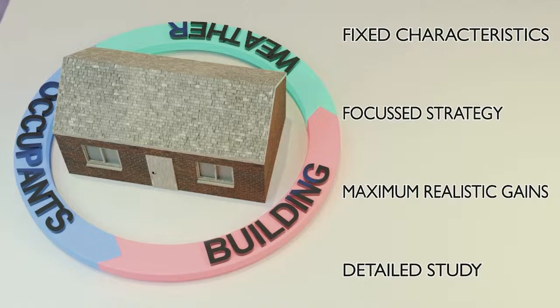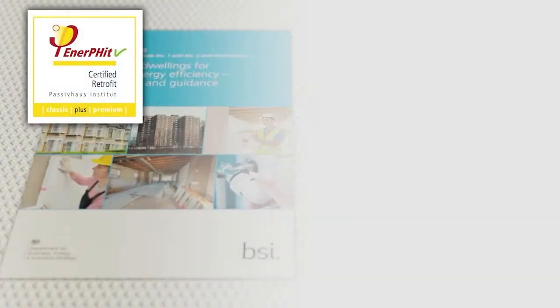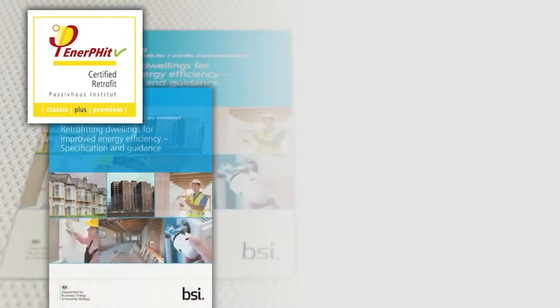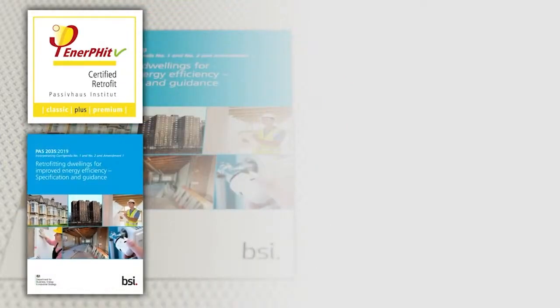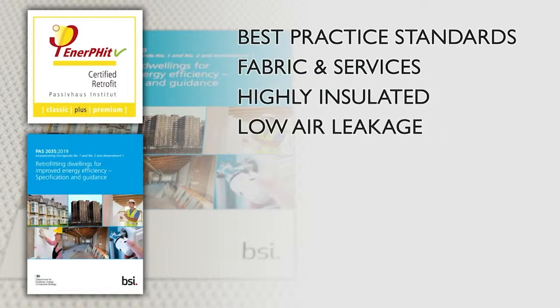To develop this understanding of the problems and solutions, two useful references are the Passive House Institute's Airtight standard and the PAS 2035 document, Retrofitting Dwellings for Improved Energy Efficiency. These two documents address the issues in retrofit from different perspectives and taken together help develop a flexible and pragmatic approach to the delivery of best practice in retrofit. Airtight, being derived from the Passive House approach, focuses on illustrating best practice performance targets for building fabric and services, with the particular focus on good levels of insulation and minimum air leakage that characterises all such projects.